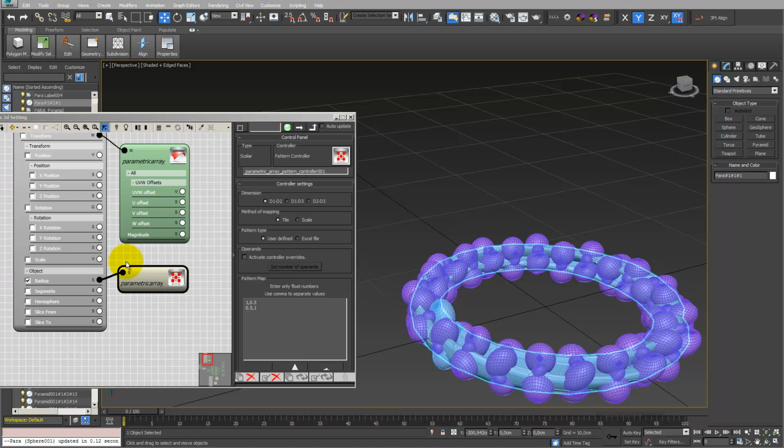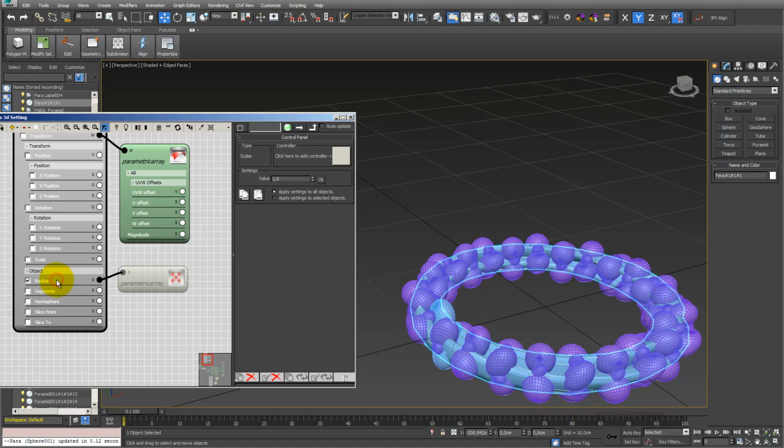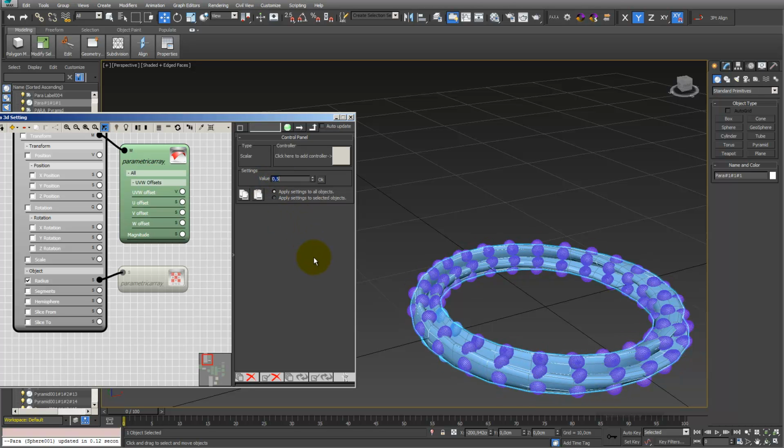The next function is also quite handy. If you select one para node, for example this controller, you can say turn off the node, and you can see that it's slightly transparent. And if I go now on radius again, then you can see that you can have influence on the value, and say probably I want 0.5, and then all the spheres go to 0.5, and this controller doesn't have any influence on my radius value, and I can turn it on again afterwards.